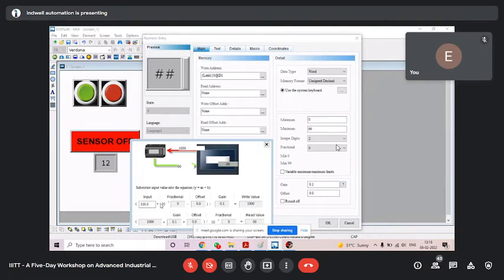According to your value, they will calculate and give you the gain value. In case of preset value, it is multiplied by 10, and in case of accumulator, it is divided by 10. So you will have to check that in its detail. It will be given everywhere. So check the detail and calculate what the value would be.